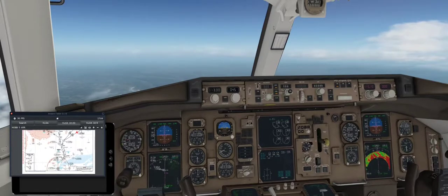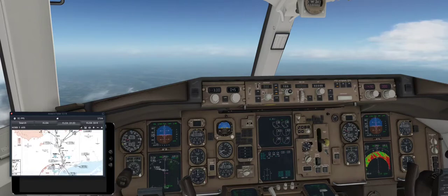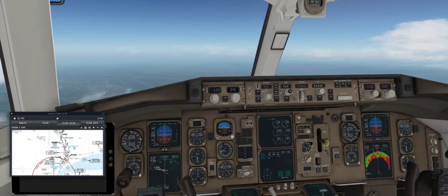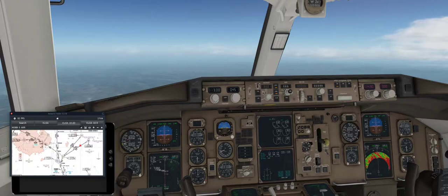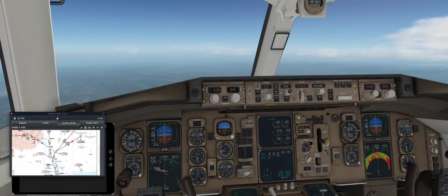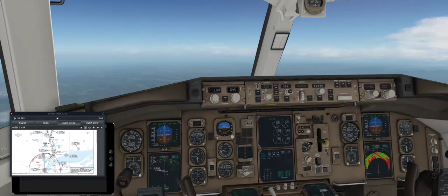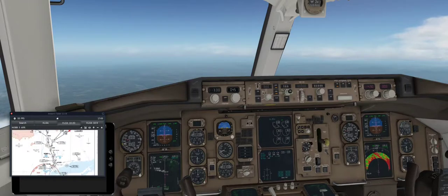Alright, so while we descend and we're on our way here, we're going to look at this approach a little more. You see there's a few points here where you might typically be told to hold. We might do one just to kind of demo it, but we're not going to do more than that. And you can envision, what is an arrival? It's an agreed upon way of funneling aircraft from several directions, all into this New York airspace, to start lining them up and stacking them so that everybody gets their turn at landing. So you might be asked to hold because the aircraft in front of you is slower or whatever, and air traffic control will instruct you to hold so that there is spacing.